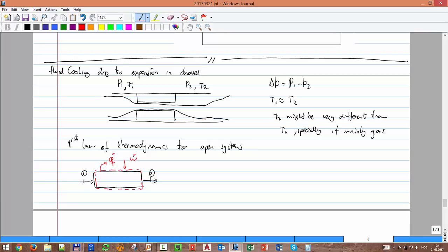Yeah? If we say that's a piece of pipe, there is actually no work, just heat being lost to the environment. If that's a pump, for example, that one is negligible, but the work, the power that we are introducing to the fluid, is important. So that expression was, if you remember, or if I remember correctly, Q minus W equal to mass flow of (U2 + P2/density + Z2 + V2²/2 − U1 ...) yes. Okay, that brings some memories. I'm not sure if good memories or bad memories, but memories. That should be g. Okay.